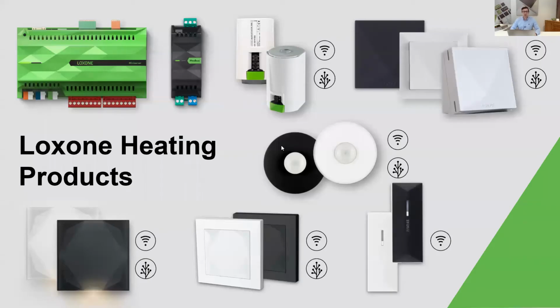Other products related to it, motion sensor. We see these all the time. Core thing about the motion sensor is it's not there to turn on heating. Heating takes too long. It would not be efficient, especially when you consider that underfloor heating with concrete screed could take a good 3 or 4 hours to actually heat that screed up. If we're turning the heating on every time we walk into the room, we're throwing money down the drain.